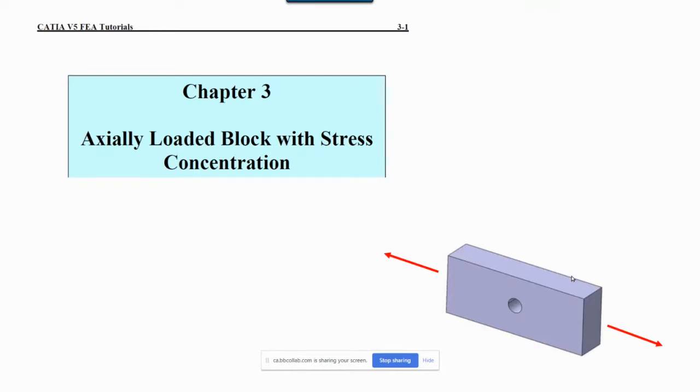Yes. On the smallest cross section? Where? You're right. The diameter of the hole, yeah. At the center. Okay, but let me ask you this. I have a hole here. It has a boundary, right? There is this circle. Where do you expect the biggest stress to be on this circular boundary? At the top and at the bottom of the circle? Yes, that is correct. At the top and the bottom.